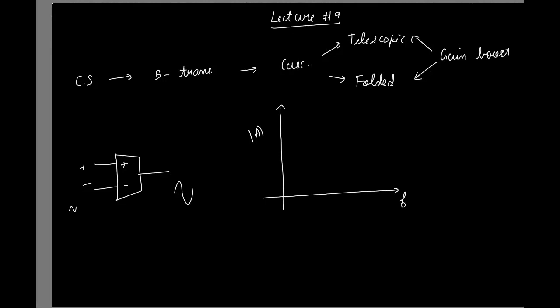I'm saying, let's say I try to measure the gain starting from low to high frequencies. Everyone is convinced that at high frequencies it should drop, right? How it drops, that's something we don't know yet, but at least it makes sense that it should drop. And why is that? Because the MOSFET, although it looks quite simple like this, has intrinsic capacitors across each of these terminals, right?